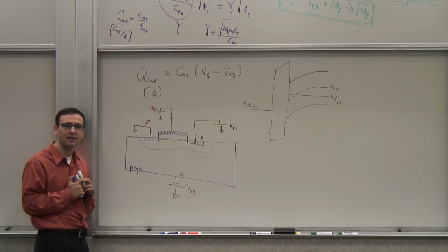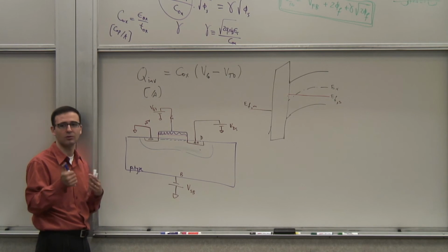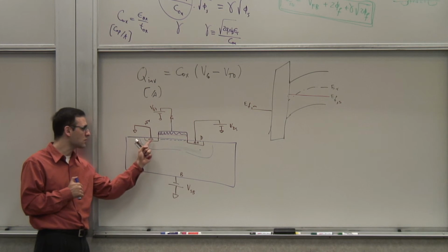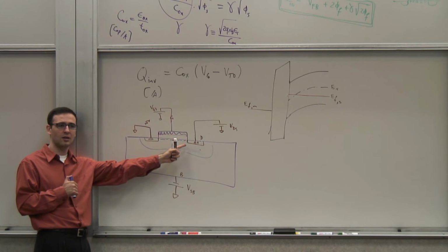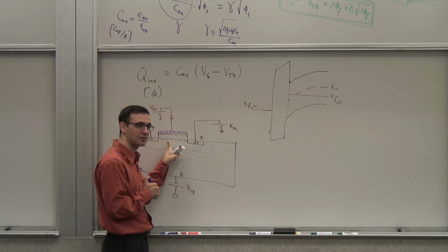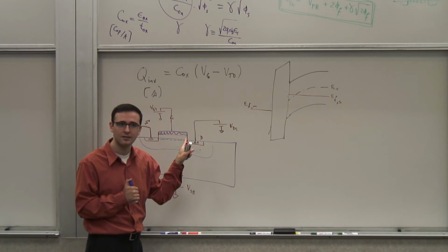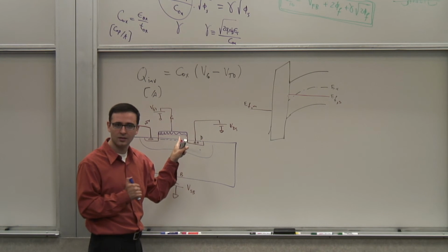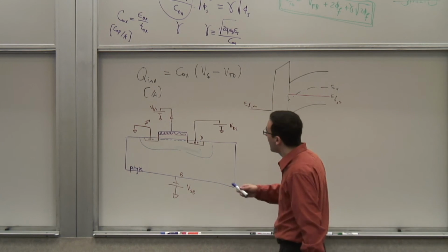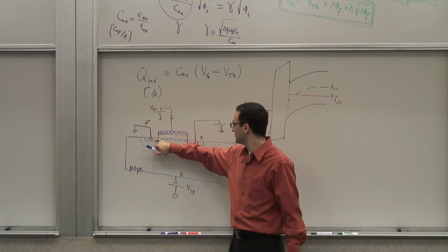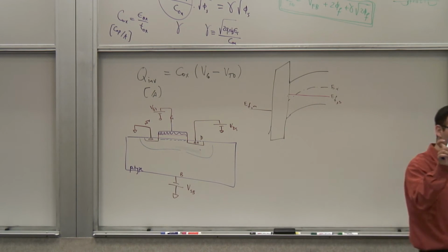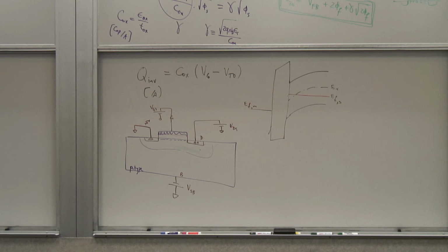Do they have to be thermally generated this time? I mean, of course, a few of them are generated thermally anyway. But now I have a source of electrons right next door. I have these huge sources of electrons, the way I've designed this device. Therefore, I can generate these electrons and dissipate them very quickly, unlike the MOS capacitor. So, although the MOS capacitor was very slow in responding, creating this inversion layer charge, this device, because of the abundant electrons available in these source and drain PN junctions, can be turned on and turned off very quickly.